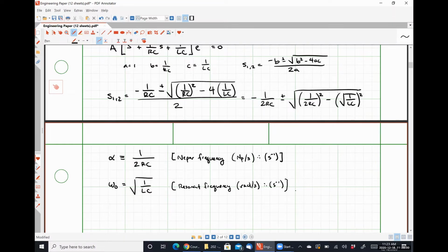There's multiple different ways to interpret it. One particular thing about the resonant frequency is, if we found the resonant frequency of a circuit in a sinusoidal steady state system, it is where the impedance of the network is purely real. So at resonance, the capacitive reactance cancels out the inductive reactance. Another way to think about it, specifically in filters, is that this is the frequency at which you get maximum amplitude.